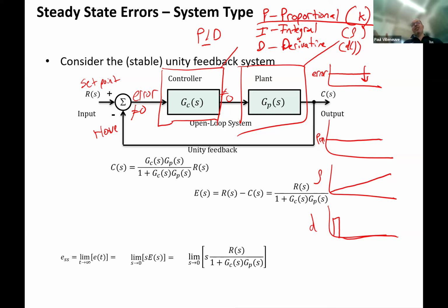So you're blasting this thing with lots and lots of heat, and then your system finally catches up, and now you get your set point, whatever your set point is. But because you've been blasting it with heat for a long period of time, you actually will overshoot your temperature, and then you have to go back down. So what you have is an oscillatory response. You're always hunting, trying to get that value.